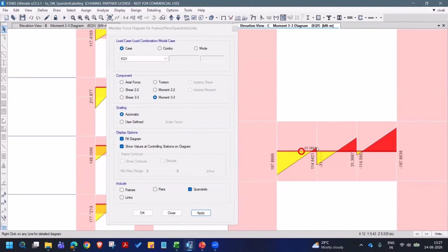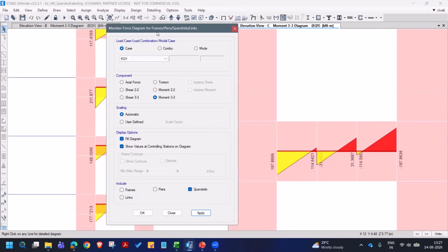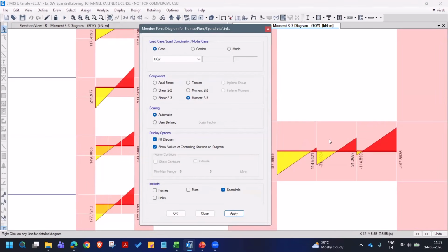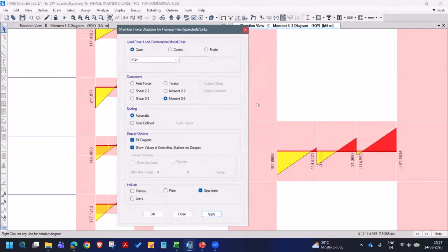So when you're using different labels, do not use the diagonal reinforcement output, because that is a default. It is enabled when seismic forces are involved, so that will not be applicable. That output you should not use, because it is a longer one anyway, and that will not be required. Only barring that output, you can use the rest of it by understanding what the design procedure is.